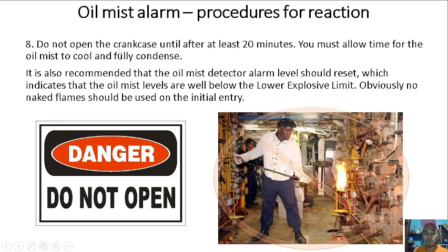Do not open the crankcase until after at least 20 minutes. Let it cool down first. You must allow time for the oil mist to cool and fully condense. It is also recommended that the oil mist detector alarm level should reset, which indicates that the oil mist levels are well below the lower explosive limit. So wait at least 20 minutes, but if the oil mist detector alarm is still active, do not open the crankcase.